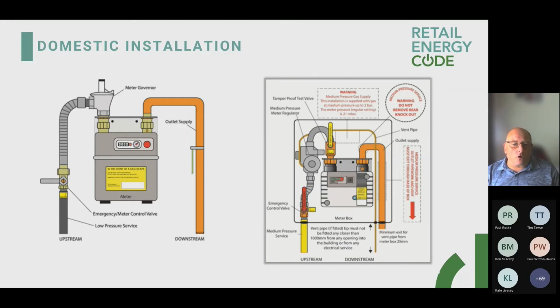But you've also got on this what they call a slam shut. The slam shut is designed so that if the regulator fails or something happens and the pressure at the meter point is too high, the valve automatically closes. It's what they call a slam shut valve.